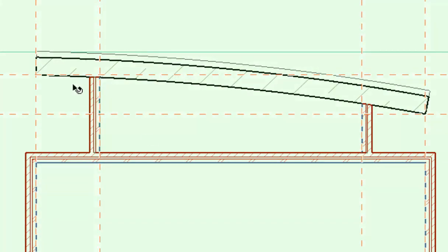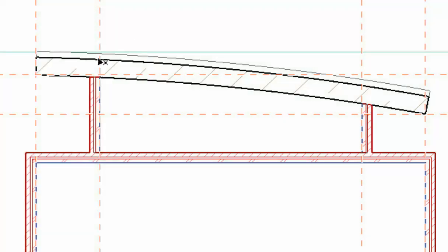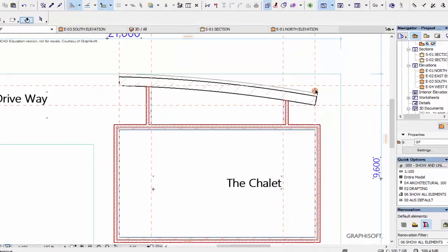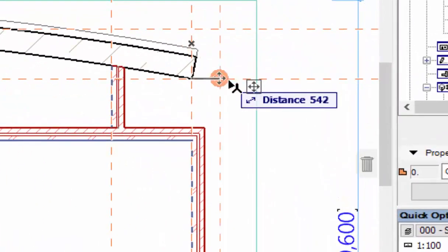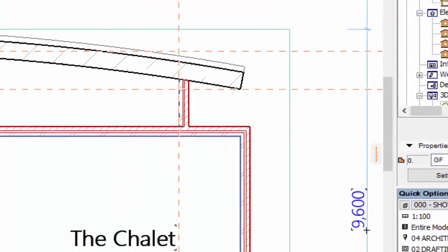So these are the things, once you're aware of that, you can go ahead and change the properties of your walls and materials. Now, like I mentioned before, to get rid of our guidelines, we just hold the cursor on until the orange circle comes up, drag it over, and the bin will appear, and you can just put your guidelines in the bin.